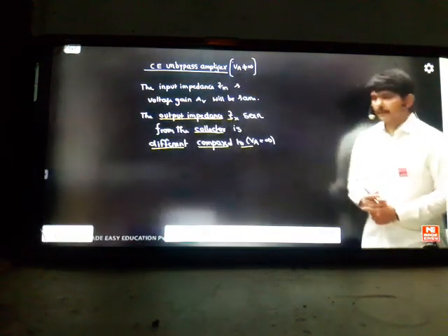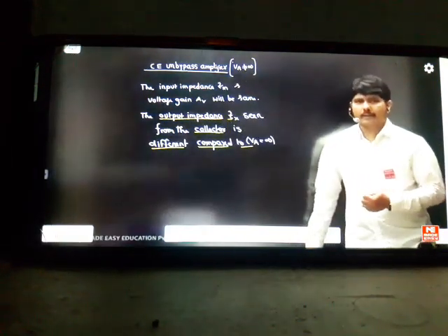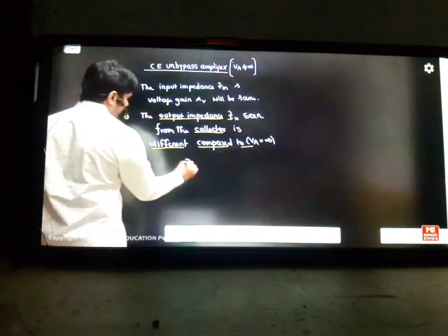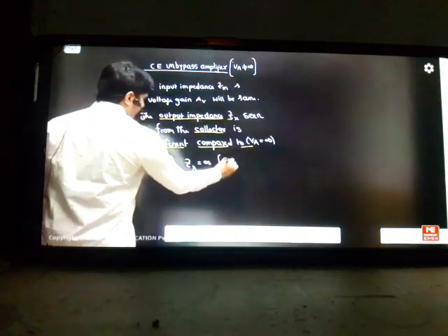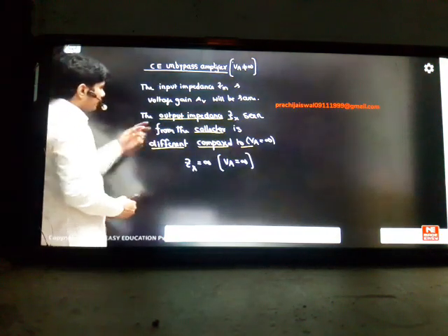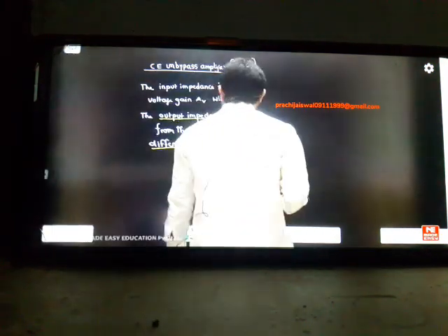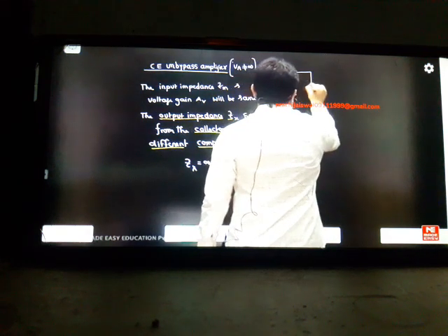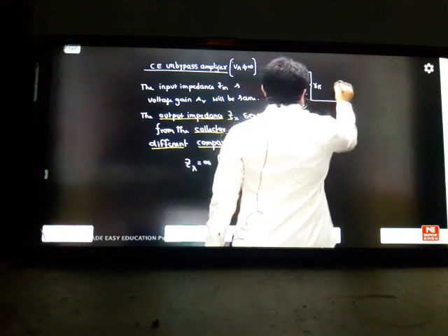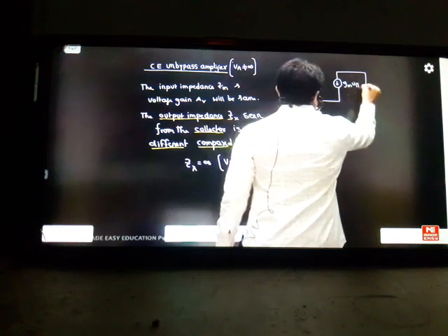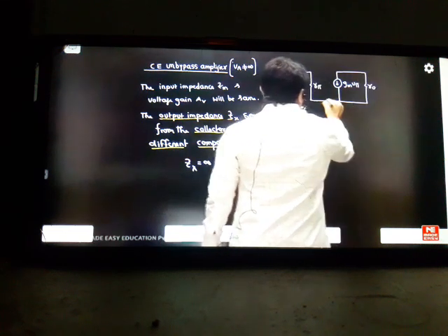Okay? With VA equal to infinite, what is the ZX value we got in the classes? Infinite, we got directly because the current source is open there. But here what is happening? Actually we got ZX as infinite when early voltage is infinite. Seen from the collector it is infinite. But now whenever I take this effect, what happens? So let us start analyzing the concept. For the output impedance, when you are solving, you will get a ground here. Next we have R pi. Next we have the current source gm into V pi. The only thing is here, one extra R0 will come, R0. And we have some RE.